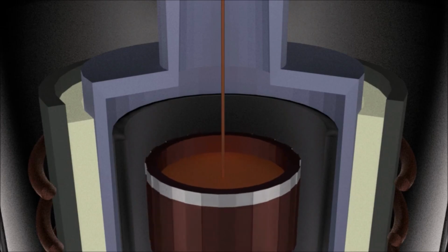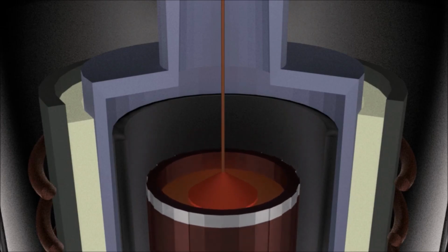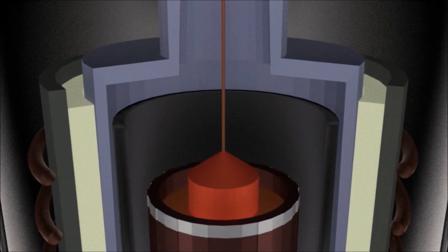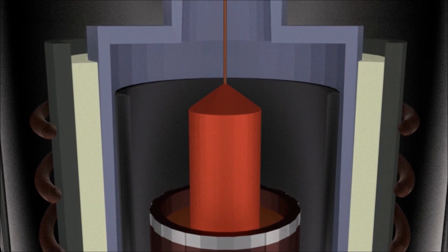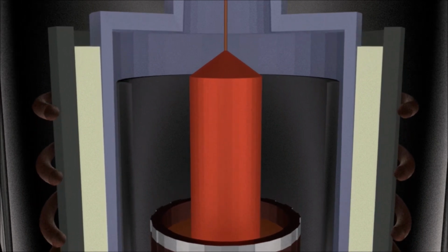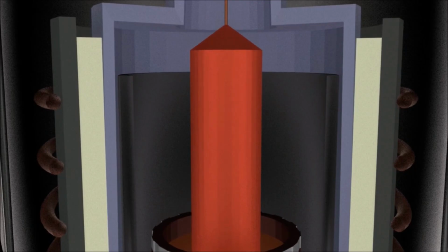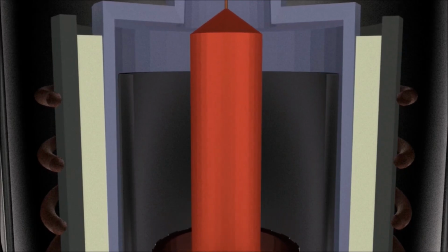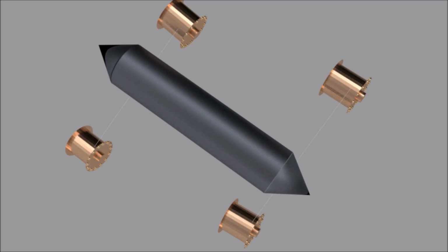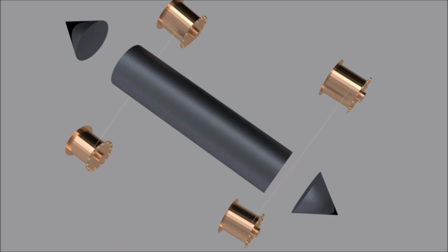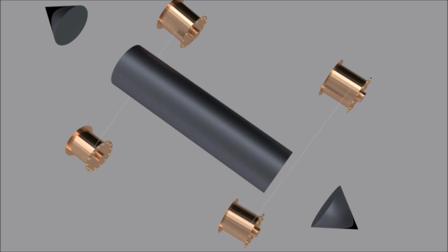After the purification, extremely small residual impurities still exist inside the molten silicon. But many of these atoms do not integrate very easily into the perfectly ordered crystal lattice. As the ingot slowly grows, the crystal tends to reject part of these impurity atoms, which remain inside the molten silicon and then progressively accumulate near the final portion of the melt. This is why the impurity concentration becomes much higher near the tail end of the ingot. For that reason, these regions are often removed or processed separately in order to preserve the highest purity material.